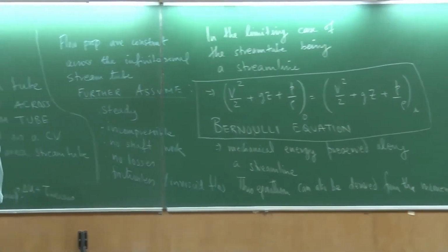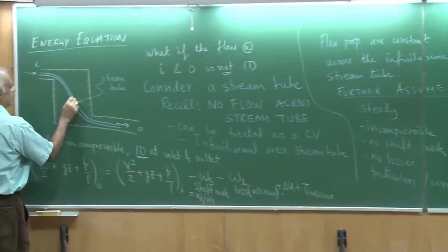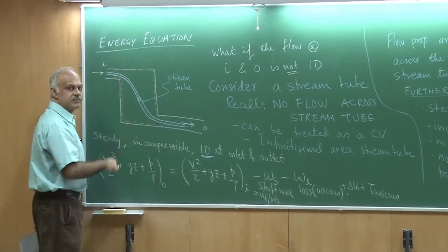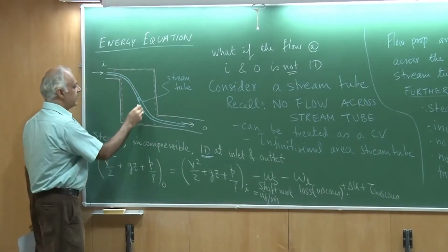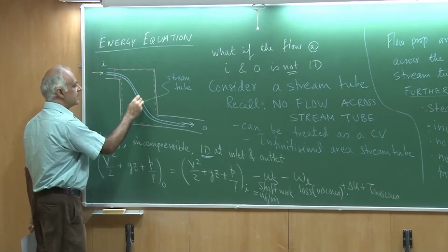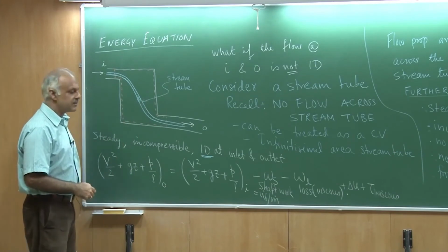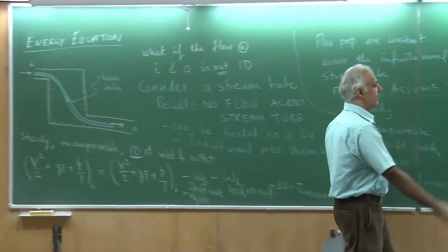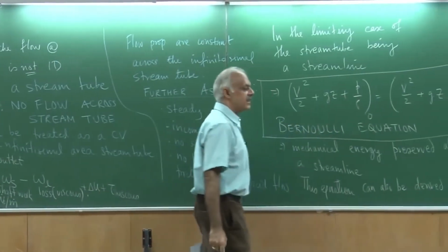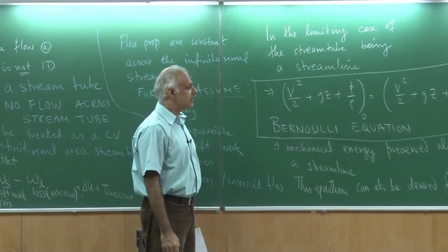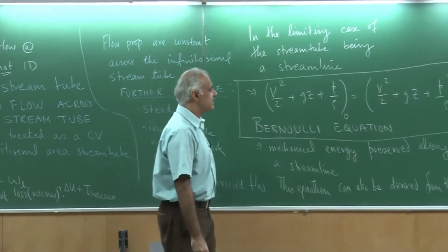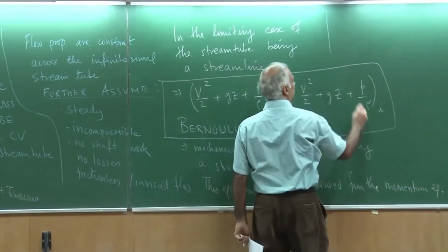So, as a fluid element moves along the stream tube, along the streamline, it has to do certain work against the pressure. So, there is a pressure acting on it upstream and downstream, and that appears as this term. This is the additional term that you would get in fluid mechanics, which you do not see in dynamics of projectiles without air resistance. Good.